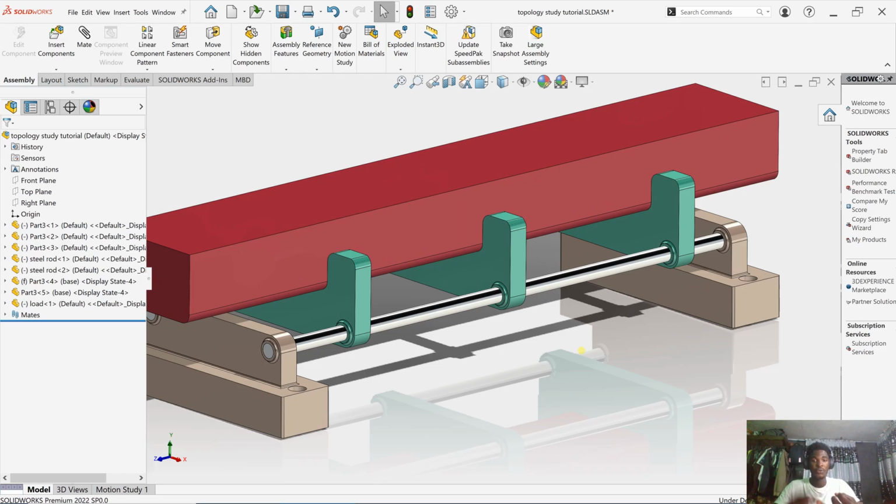Okay. So you see, by doing that, by removing the mass, because when you're 3D printing with FDM printers, you see that the more the mass, the more filament is going to cost you, and the more the time it's going to take for a print. And when we are dealing with FDM printers, we hate, I don't know, I'm going to speak from my own perspective, I really hate long prints.